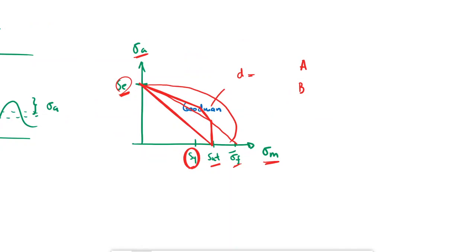This was just combining both torsion and sigma into a von Mises stress, and then factoring out everything that was not the mean torque, alternating torque, mean moment, and alternating moment. Okay, so these two are going to already include things like the KF and the KFS.